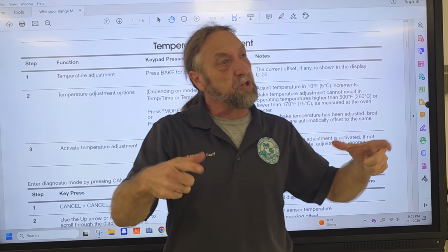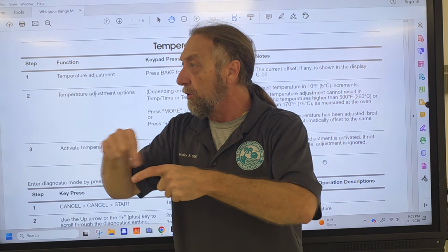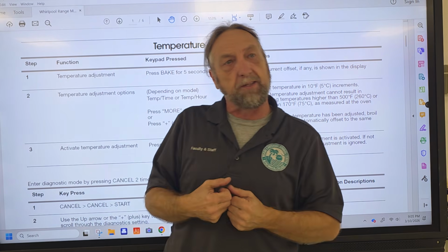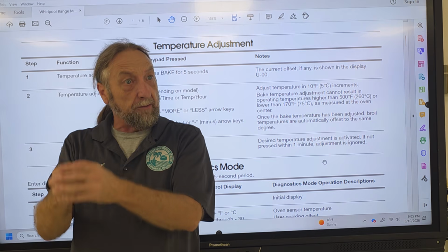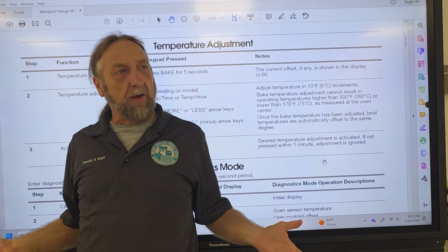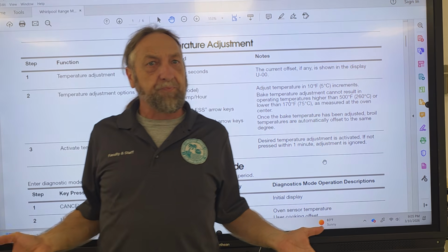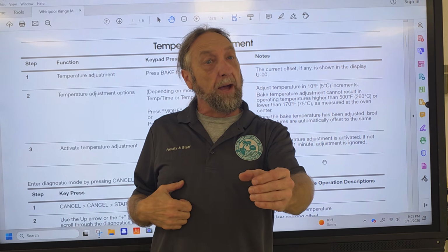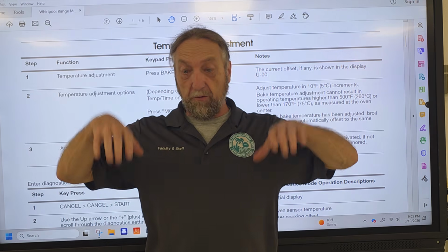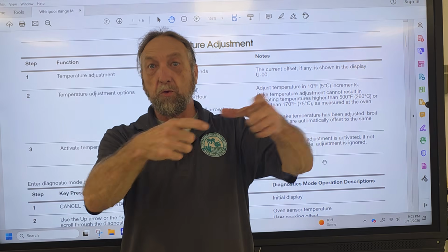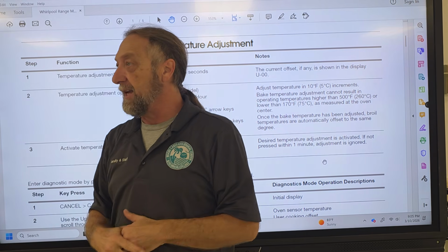You know, on some of the stoves, they have the coil burner, the old school burner, not the glass top. And when you work on the stove, one of the things I tell you is check the oven vent. And why am I telling you to check the oven vent? Just so you know there's a vent there? No. A lot of times the oven vent is right where the left rear burner is. You have 4 burners, and there's an oven vent on the left one, and it comes through the hole of the pan and lets the heat out of the oven.